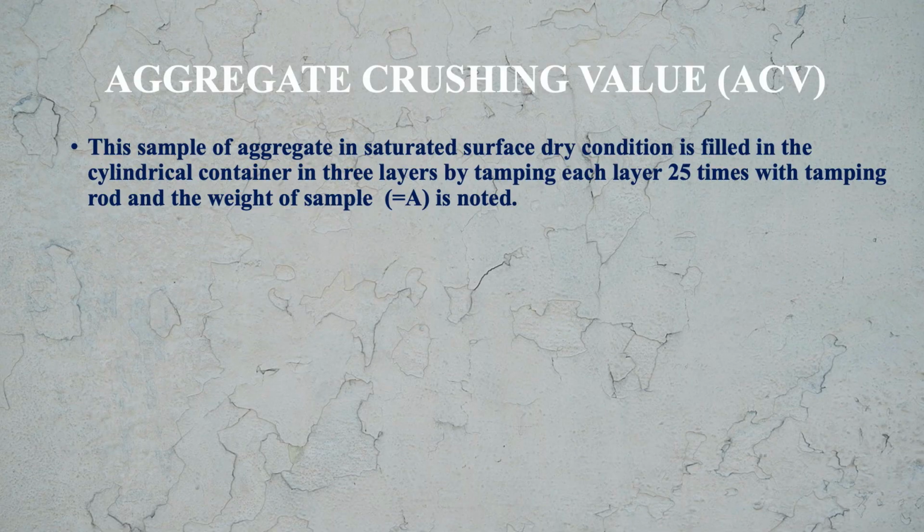This sample should be in saturated surface dry condition. As you know, you first saturate the aggregate in water, take it out, and the surface is dried.